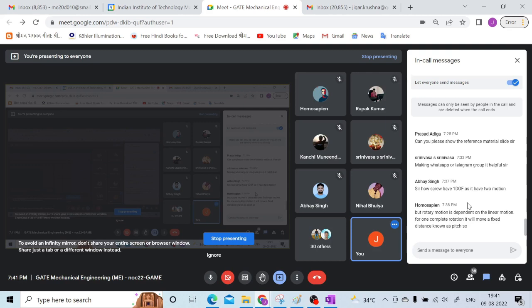Here we have this kinematic chain and then mechanism, right? So after having an idea about the kinematic chain and mechanism, we will go for degree of freedom. If we go for degree of freedom, then in 3D, if you have any object, what are the possible degrees of freedom? That will be 6, right? Because it can have translatory motion along all 3 directions, and similarly rotational motion about all these 3 axes, right? So this is how you have a total of 6 degrees of freedom, right?